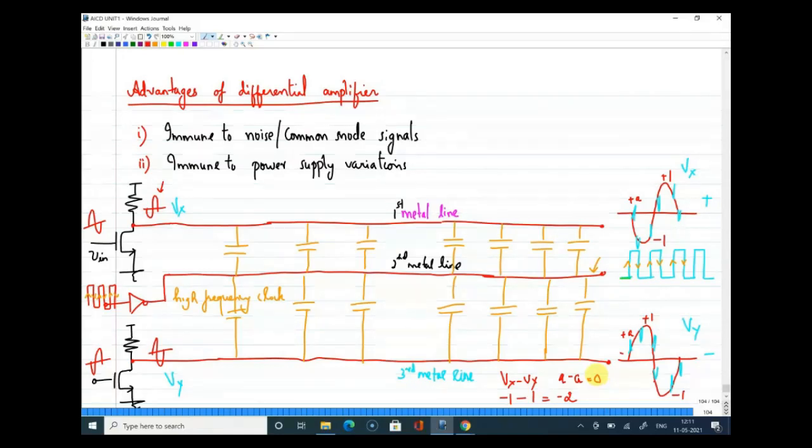All right. Now you had asked one more question. Do these spikes cause distortion? Generally we say a distortion is when there is a change of shape of the waveform, or whenever the shape is not preserved. But what you can see here is the signal, the sinusoidal variation is there, and upon that you have a spike. So when you do proper differential signaling, if the spikes are getting cancelled, the signal will not be distorted at all.